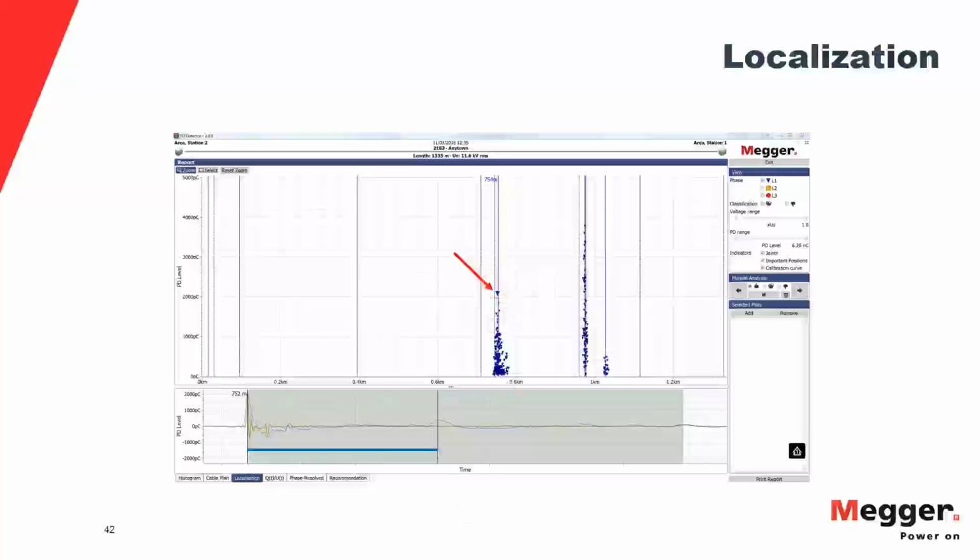Once that pulse arrives, it stops the timer, and it can calculate a distance. It can calculate a time between the 2 pulses, and if we know the speed those pulses were traveling, we can calculate the distance. Of course, in this example, I slowed it down so you guys can see. It doesn't really stop at the end. These signals don't stop. They flow smoothly through, but I slowed it down so you guys could follow along. What you might notice here is that our initial pulse and our reflected pulse look similar, but my reflected pulse is considerably shorter and a little bit wider than my initial pulse. And we call that effect cable attenuation and dispersion.